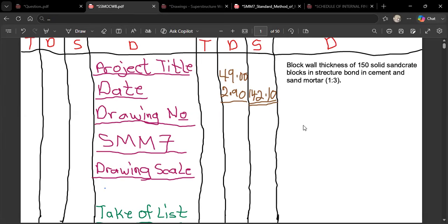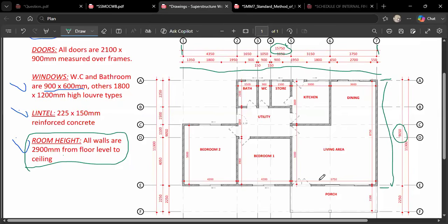That is our description for the takeoff that we did. It has got windows. If you come over here, this has windows. For the external walls, we are taking all the external walls in the height, or we've taken the area, but even the area itself has windows. So we have to deduct the windows.